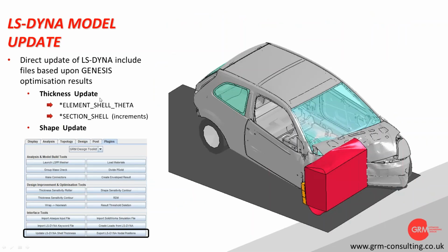And then I think this is the last update in the Design Studio interface, and it's relating to LS-DYNA based optimization studies. I think it's relatively common to linearize a nonlinear case. People do it quite a bit, be it in the example I'll go through here with an automotive body, or even just a small component where you may perform an approximate optimization linearly, and then you want to do that validation in the nonlinear model afterwards.